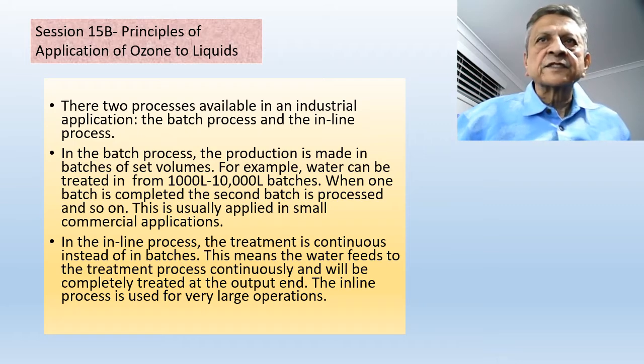In the inline process, the treatment is continuous and not in batches. This means raw water is continuously fed through the pipeline and ozone is applied within the flow of that water.